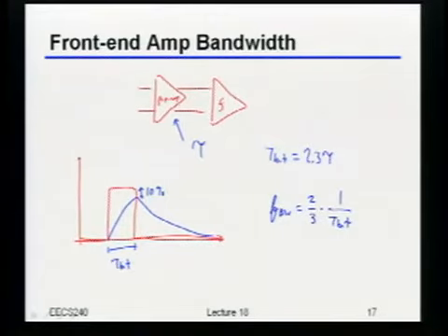So now here's the first interesting question. Let's say t bit is 200 picoseconds, meaning I have 5 gigabits per second of data. If I followed this rule, I would be saying that I should set my bandwidth at something like 3.33 gigahertz. Usually when people first hear this, they're a little bit confused, because I just said that I have 5 gigabits of data, but only 3.3 gigahertz of bandwidth. So why is it that I claim that actually that's perfectly okay?